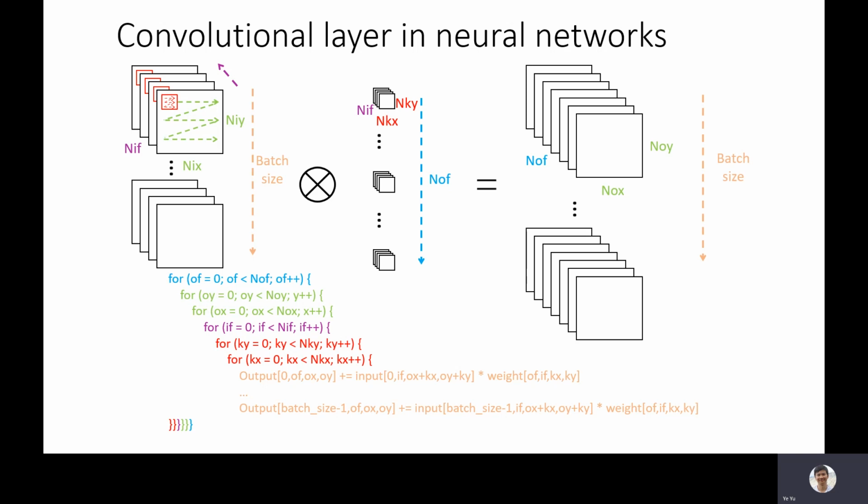The on-chip memory of the accelerator may not be large enough to hold the entire dataset for input feature maps, kernel weights, and output feature maps. Therefore, they need to be partitioned into smaller data chunks in order to fit in the on-chip memory. This is called loop tiling. The T parameters denote the corresponding design variables for the loop tiling, and they represent the size of the data chunks stored in the on-chip memory.